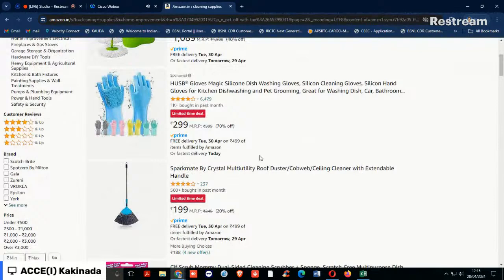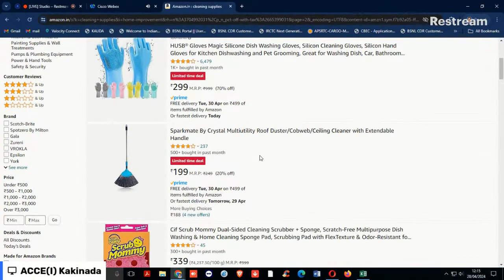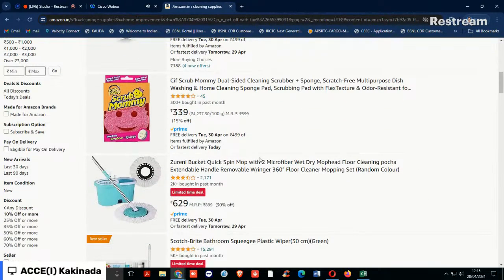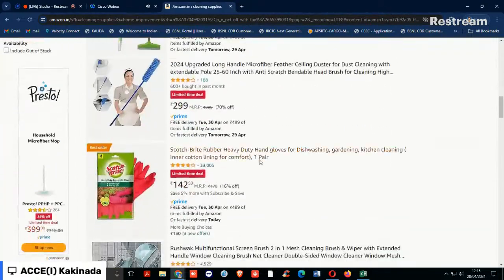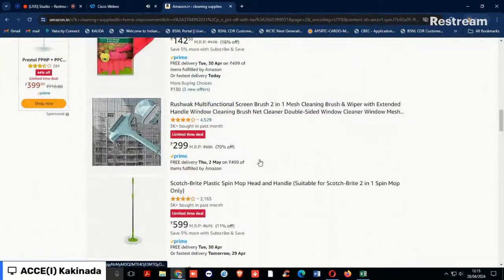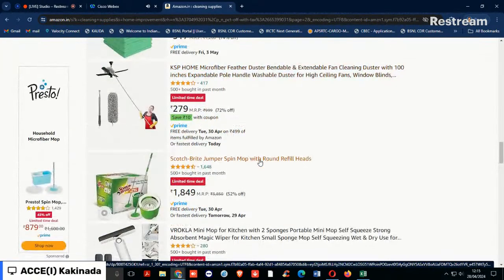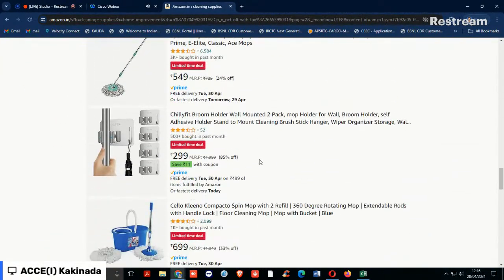Whenever we are using this, it is preferable to place minimum pipes or no pipes in the slab itself. If we must place pipes, the minimum number should be placed and should be jumped from a beam to the slab with 1 pipe only, not as a continuous network in a radial pattern or a continuous pattern. This continuous pattern will give you a lot of tension cracking. Why? Because it will intercept your yield line patterns. Yield line patterns will generally form at the ultimate loads, not at the working loads. But what we work with are the service loads, the working load deflections and the working load bending. But there is a possibility of yield lines forming under the working loads.